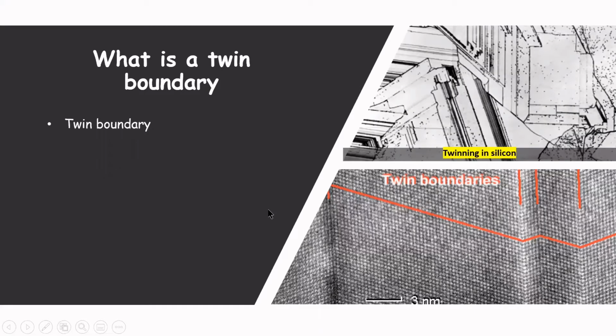In addition to slip, plastic deformation in some metallic materials can also occur by the formation of mechanical twins, or twinning. And now we have another type of boundary that we can consider as a grain boundary, because on both sides, as you can see here, we have some type of material, but this is special because it preserves the mirror symmetry across the boundary.